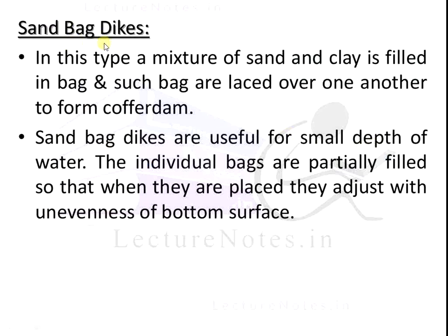Next is the sandbag dikes. In this type, a mixture of sand and clay is filled in bags, and such bags are laid over one another to form the cofferdam. The bags are laid one by one to form the cofferdam.